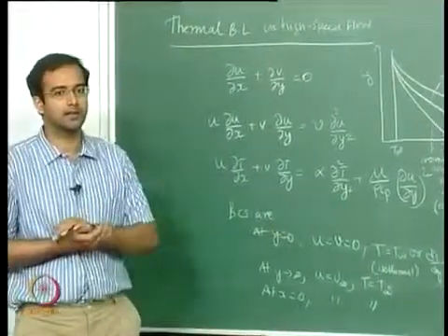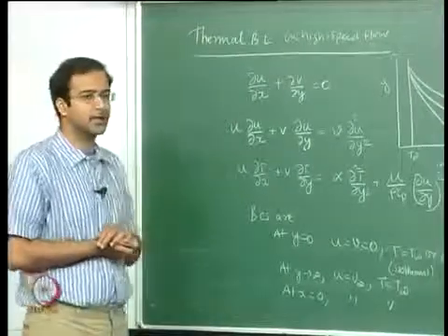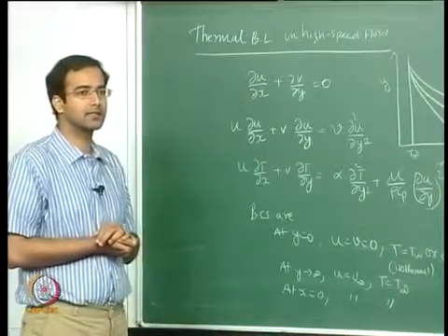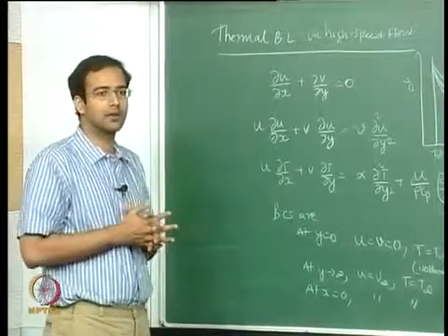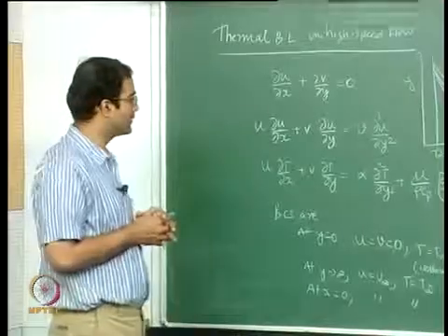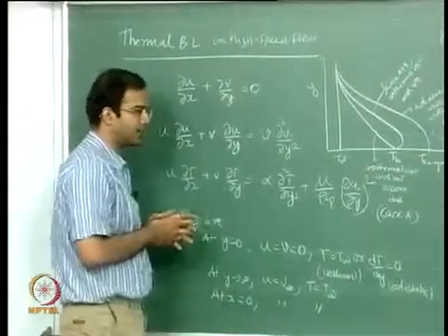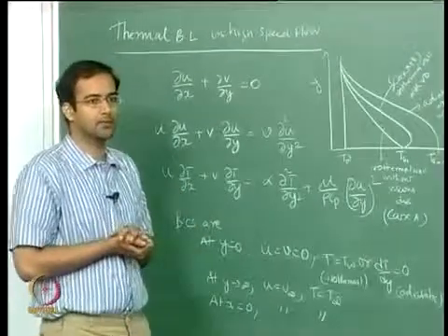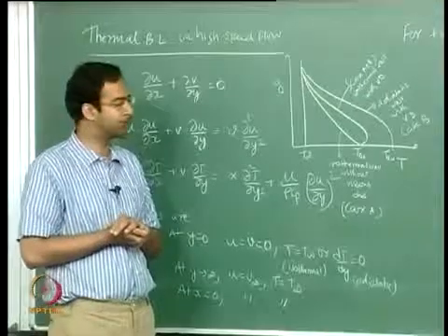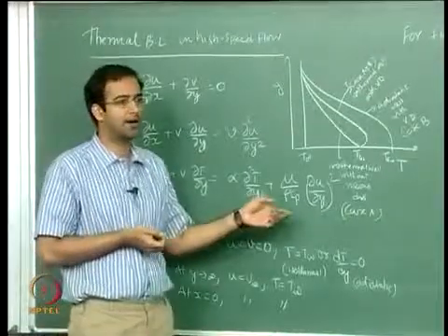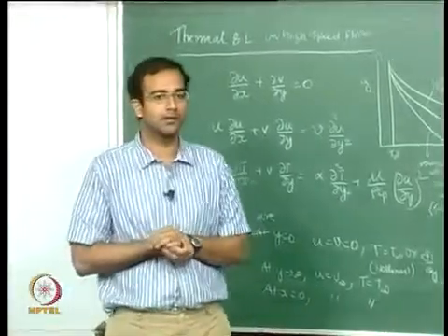Also we had looked at some of the similarity solutions for flows with pressure gradient, but still the energy equation was the same throughout in all of these configurations. So now we want to consider a case where you can, for example, apply either Falkner-Skan flows for a wedge, or you can take a simple flat plate boundary layer and see the effect of adding a viscous dissipation term. So when is this term going to be important?